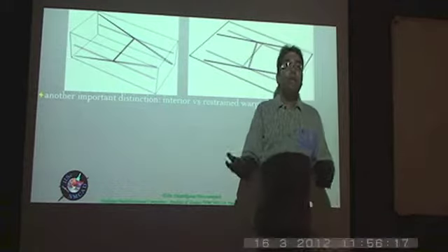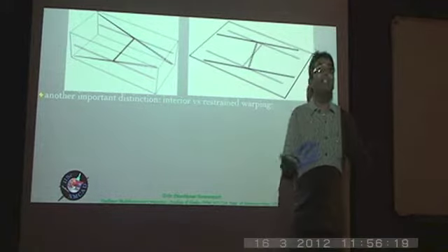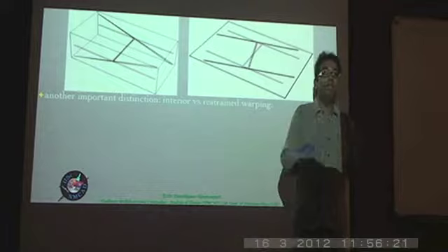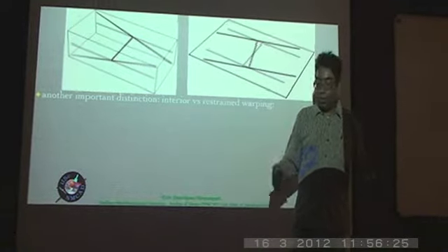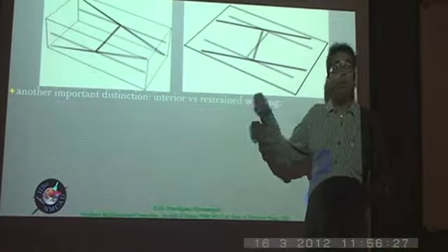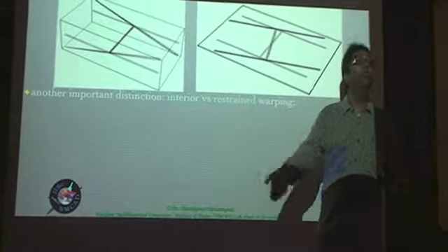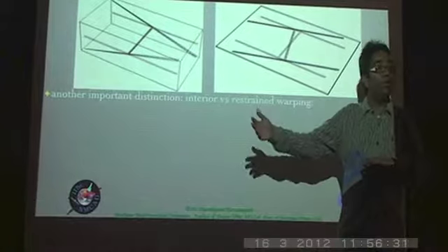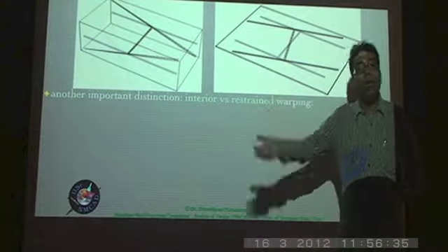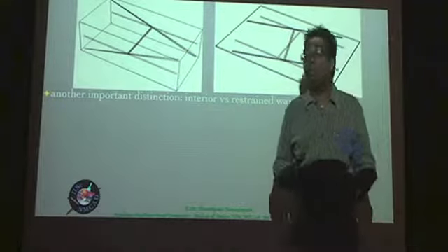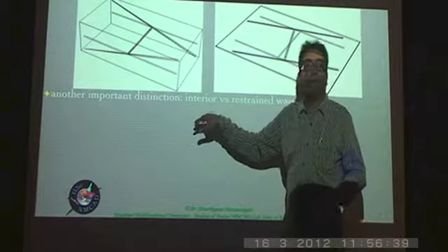So now, since we have solved for those interior warpings, what happens is that we resubstitute back into the energy, first into the 3D strains, and then into the energy, and therefore everything gets expressed in terms of the 1D strain. So no longer does the warping appear explicitly, because we have solved for the warping in terms of the 1D variables. It's the 1D variables alone which appear in the energy after the solution for the warping. So that's where the interior warping comes into the picture.